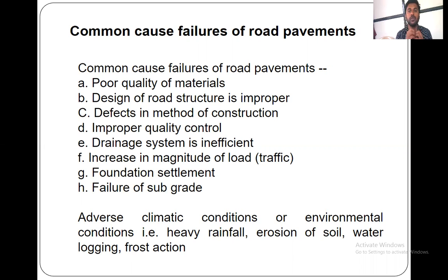Okay, the bonding between the two materials will not be proper if it is rounded stuff. So what will happen? It will break the bond between the aggregates very easily under very low load. So angular aggregate should be used. Also, good quality aggregate should be used.